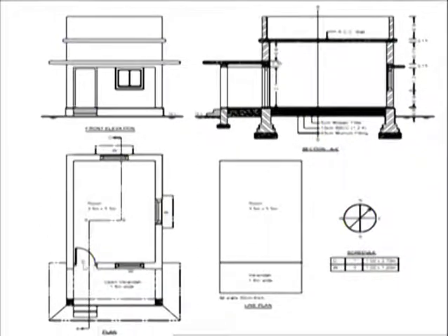So to prevent that, we have to provide the lintel and this weather shed, and for this lintel, some bearing is to be provided. So you see, for this lintel, some bearing is provided here. So the width of this weather shed is slightly more than the width of the window. That is the reason.